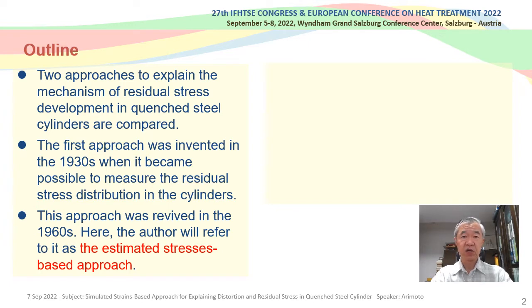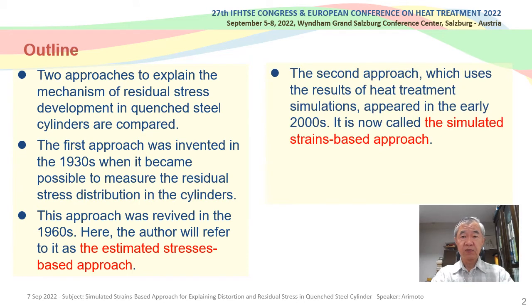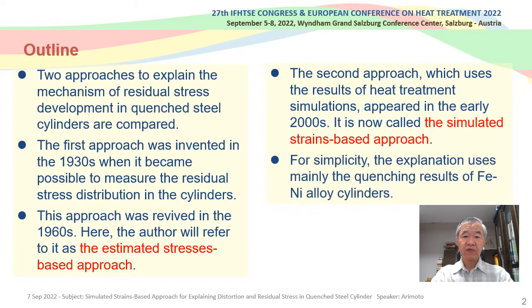stress-based approach. The second approach, which uses the results of heat treatment simulation, appeared in the early 2000s. It is now called the simulated strain-based approach. For simplicity, the explanation uses mainly the quenching results of iron-nickel alloy cylinders.